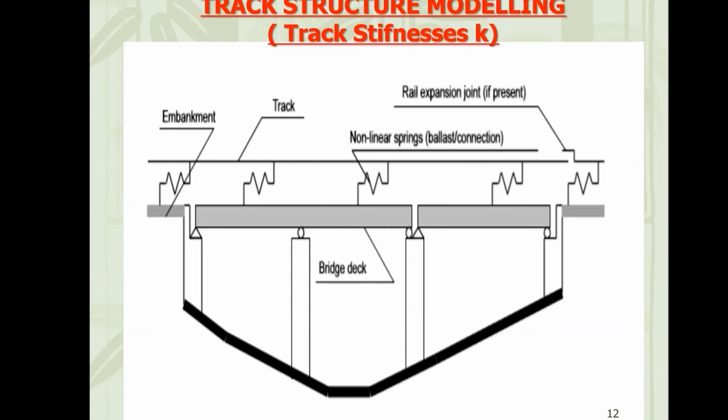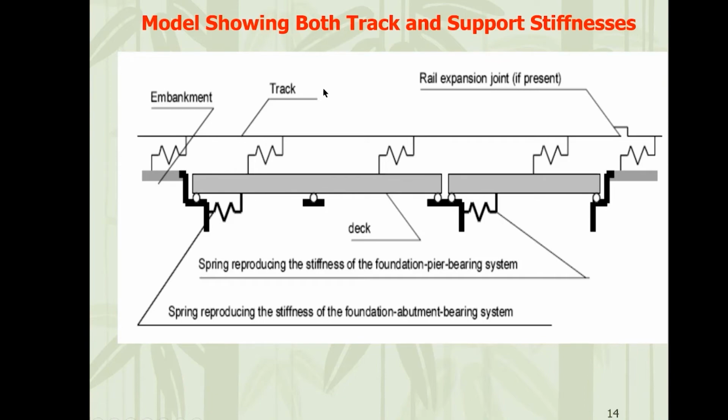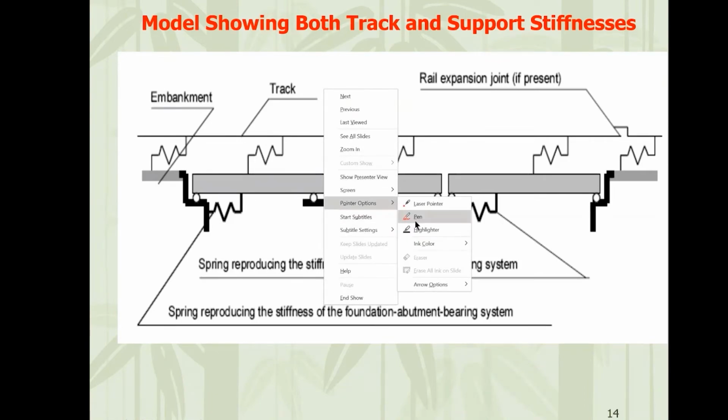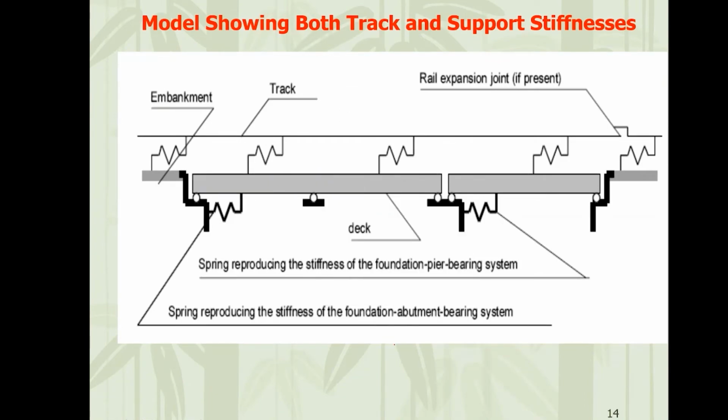Okay, so here I have a track, and the track is linked with the bridge by way of these springs, right? And here I have a switch expansion joint also in the track, right? So expansion and contraction of the rail also will take place. So there will be interaction due to that also, right? These are the longitudinal stiffness of the track or longitudinal resistance. We represent this by small k. Its values we will discuss later, right?